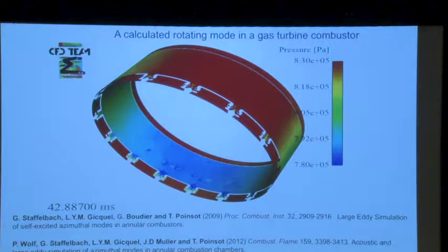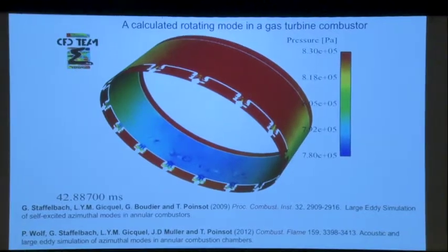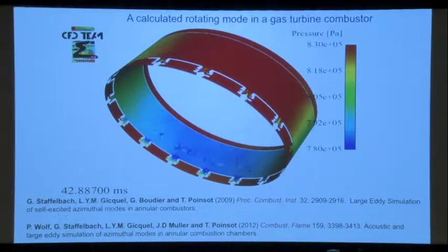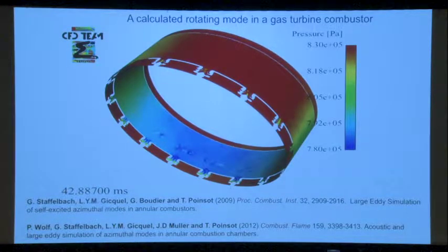And what you see is that actually the injectors respond to the pressure. As the pressure comes in front of the injector, it either gives a little more or a little less reactance. And there is the transfer function there, and there is a response.